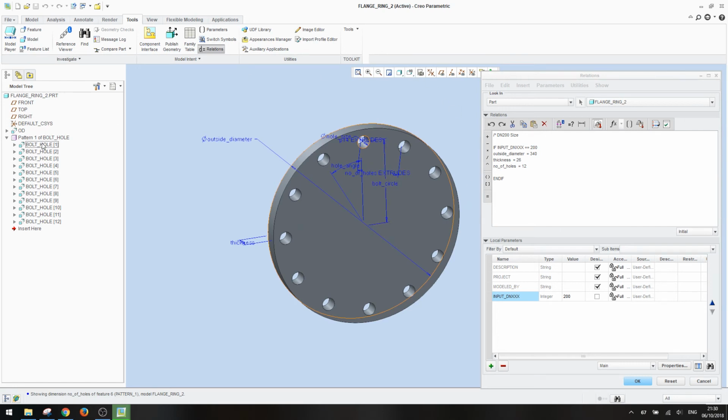As you can see, as you click through features, it actually accumulates them as you go, which is quite handy. And it can get a little bit busy. Hole size, so we said that was 22. And the hole angle here, that's going to change. You just want to go through 360 degrees divided by the number of holes you've got, which will space them out equally.